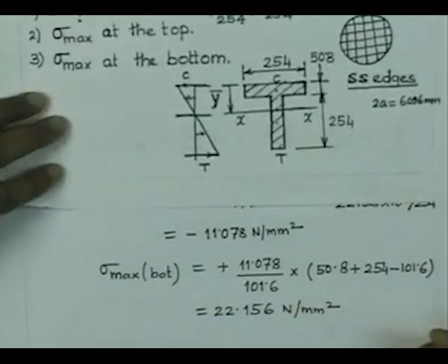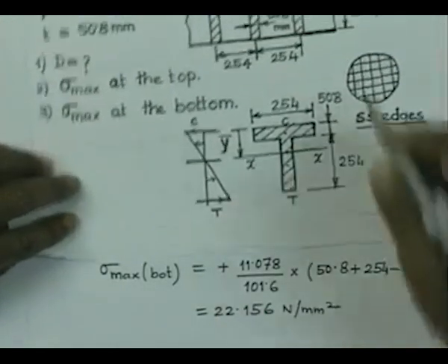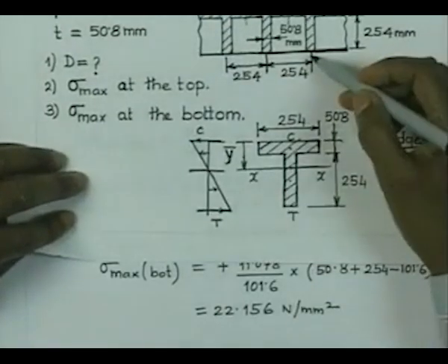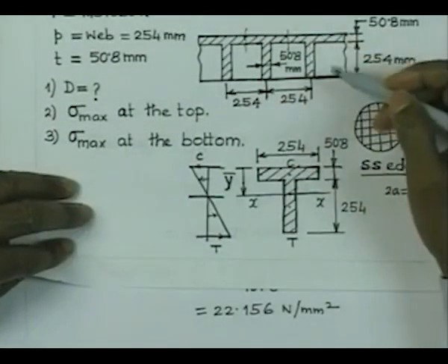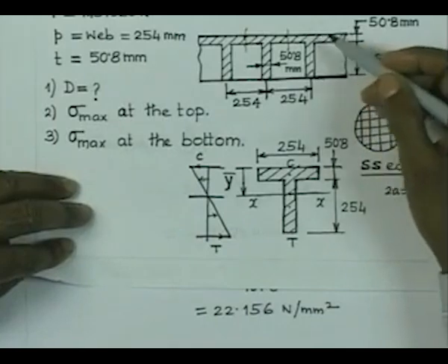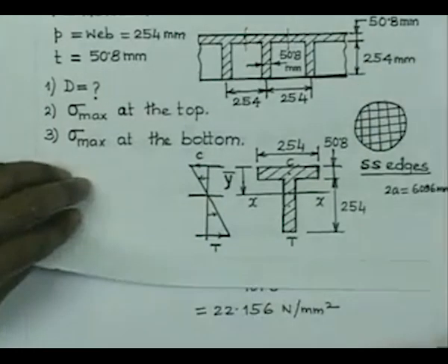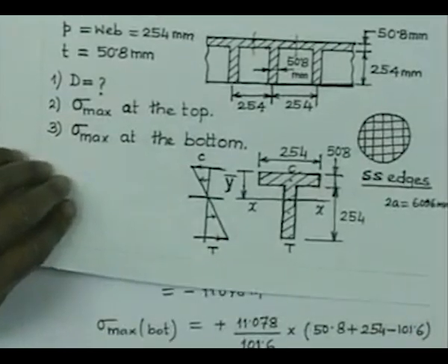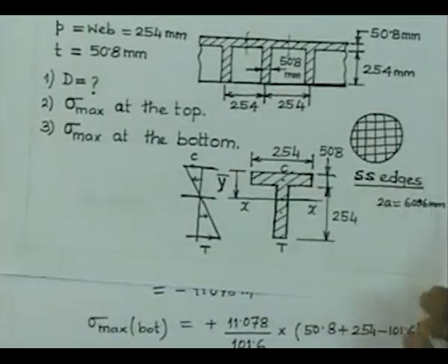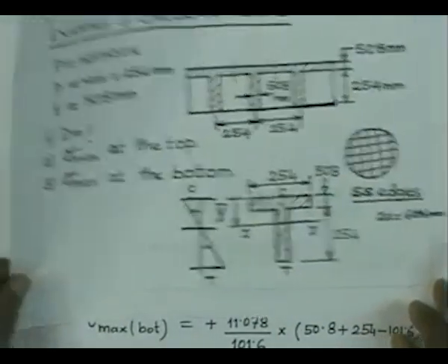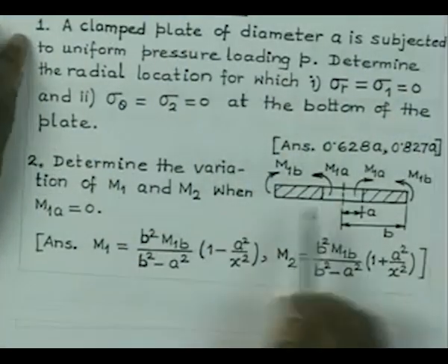You expect naturally the plate to be subjected to tensile stresses at the bottom under the action of the load at the top, and compressive stresses to come up at the top. So, therefore, we have got those stresses. So, you can solve a problem of this type, where the thickness is not uniform, by following a procedure like this. You can consider problems for solving yourself. So, look into the problem of this type.